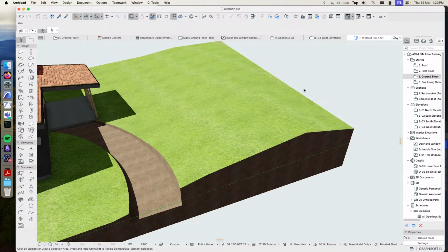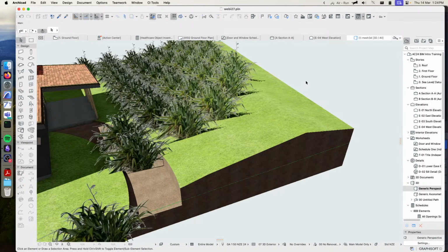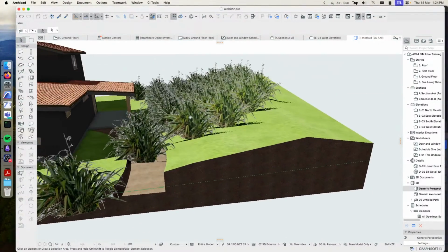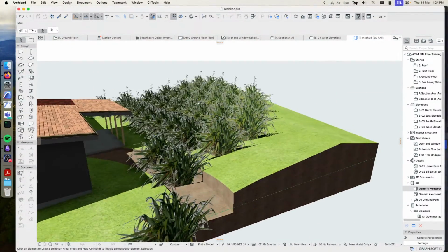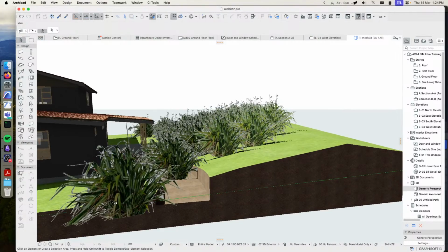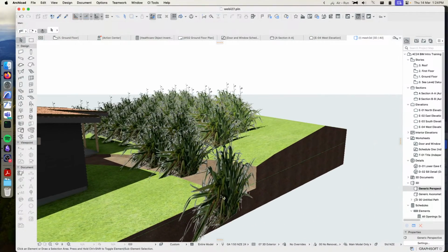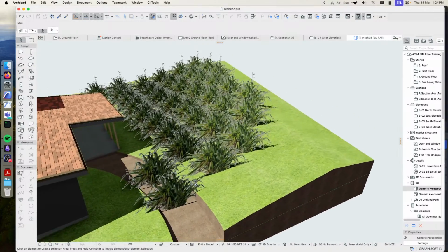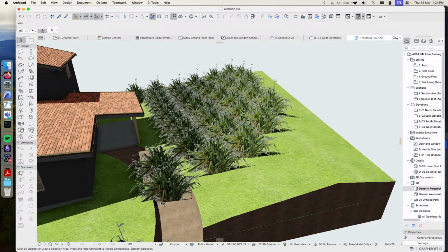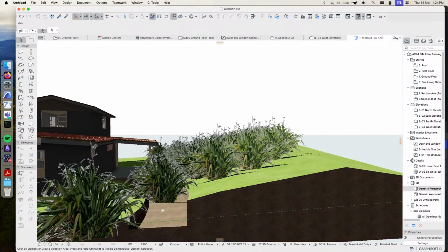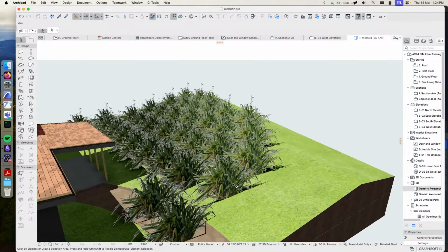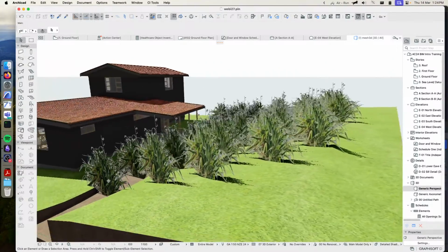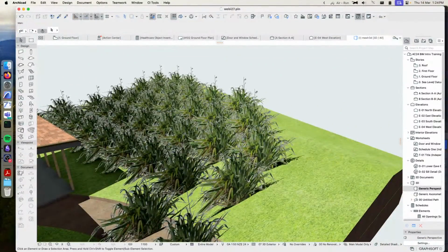And now if we go to our 3D and wait for that to generate, you should see them, unless something disastrous has gone wrong, they should, there we go, all be sitting up on the actual surface of the mesh that we had selected. This one here that didn't overlap with the mesh will just drop down to 0, but everything else will be placed on the surface of the mesh. So you can see these ones here have gone into the hole that a solid element operation cut out for a path there, but the other ones are sitting on the actual top surface of the mesh, as you would expect. So that's a great way of placing a whole bunch of objects,